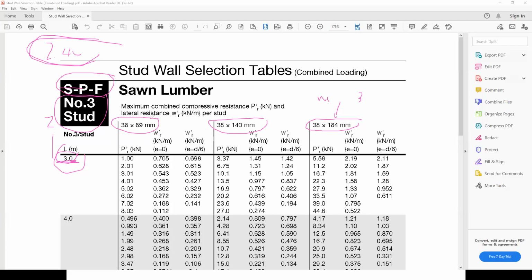Now that's #1. These are the most common ones that we use to build walls, 2x4s or 2x6s. The reason why we tend to use 2x6 is because we want to be able to create the cavity. So this is my 2x6. We want to create the cavity so that we can put enough insulation to have the right R value for our exterior wall. That's why we use 2x6s. The 2x6 is done more so that we can create the cavity where the insulation is going to go. In other words, we're going to fill this up with insulation in here. And that's why we use 2x6s.